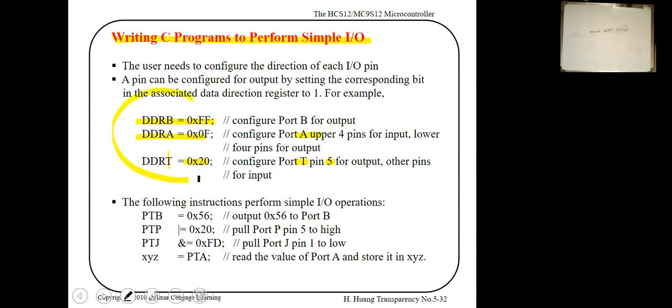Now this is how to configure. Now how to read, it's very straightforward. For example, if you want to read from port B, we used to say LDAA PTB in assembly. Now in high level, we just write PTB equals this. This is an output. For example, here PTB |= 0x02. So this implies OR port B with this mask, then store it in port B.